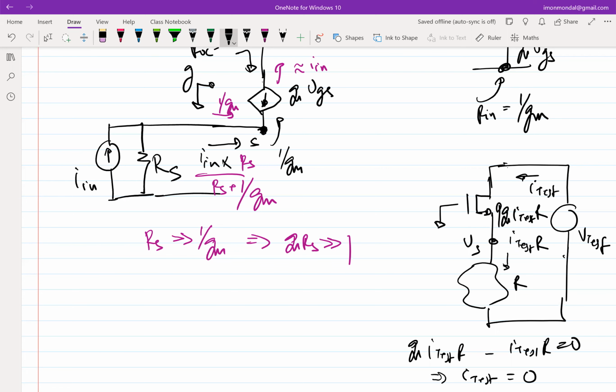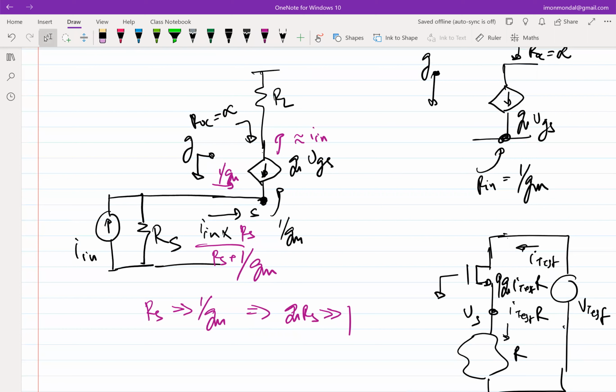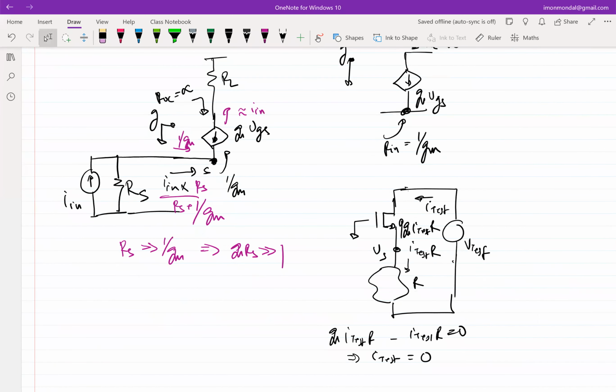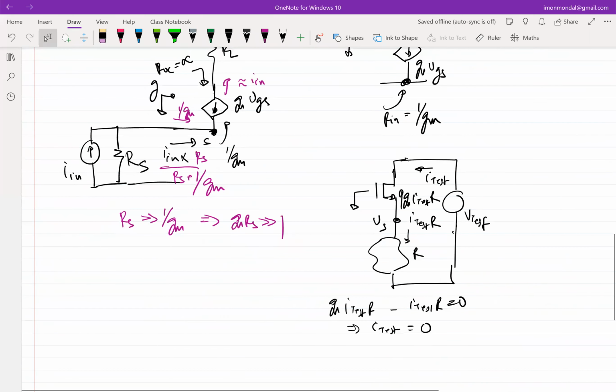Okay. So now if you are convinced that this is the contraption in the small signal sense, we have to figure out how to ensure that the circuit gets biased when I put actual transistors in. This is the incremental picture, so I need the biasing picture also. I need the total picture. So what is the thing that I need to do now? I need to replace this gm with a transistor. So what should I do?